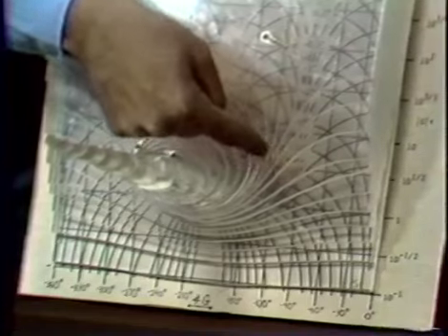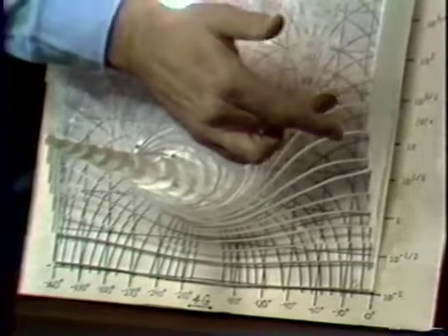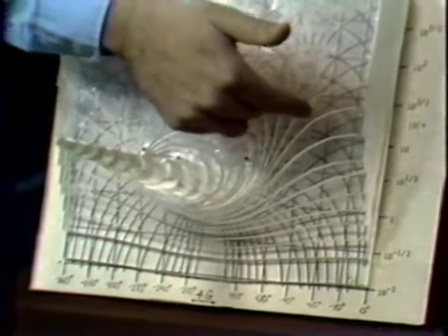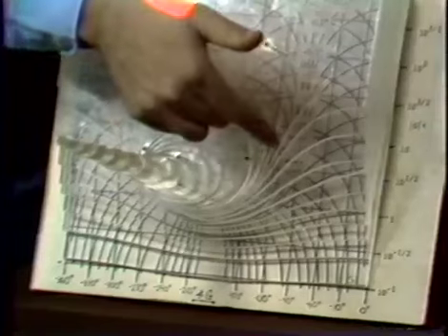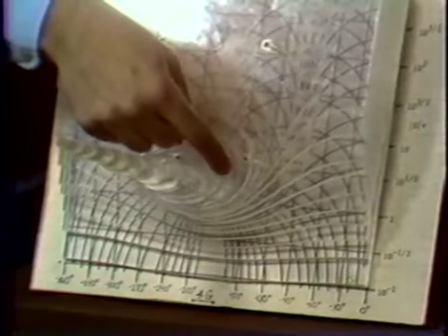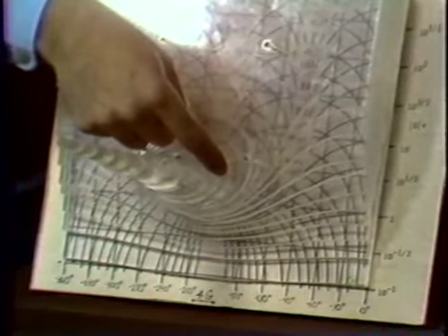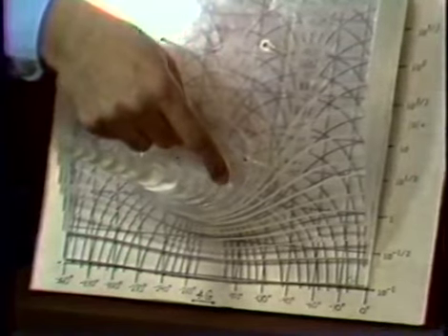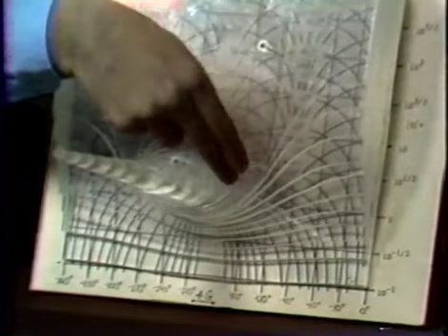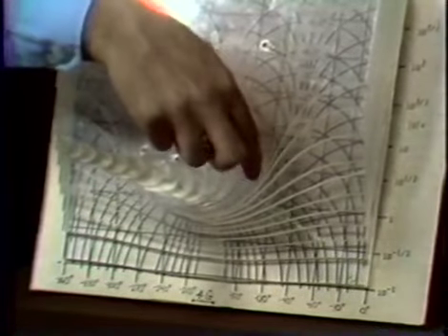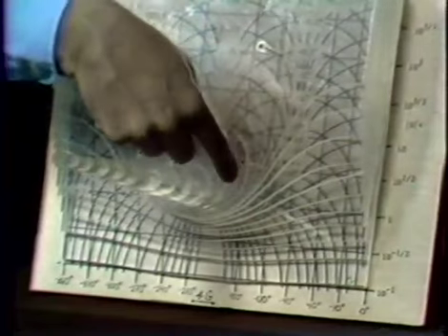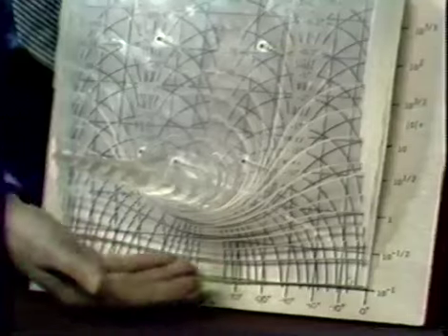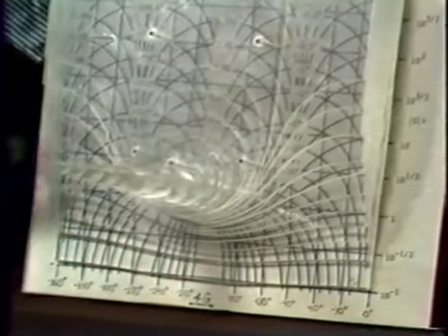And the height, the magnitude of G over 1 plus G, would be the closed loop magnitude that corresponded at various frequencies. When we had a G at this point, for example, that's about a magnitude of 1 and maybe an angle of minus 150 degrees or something like that, why, we'd find out that we had a magnitude that was this much. That's our relative elevation above the unity point.